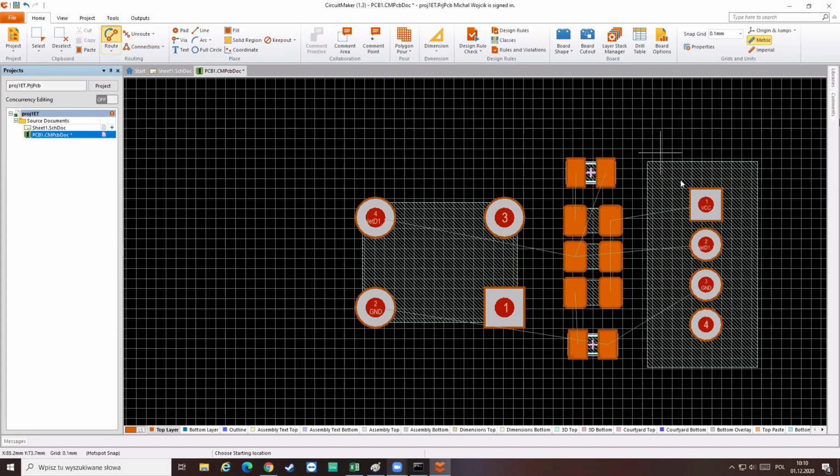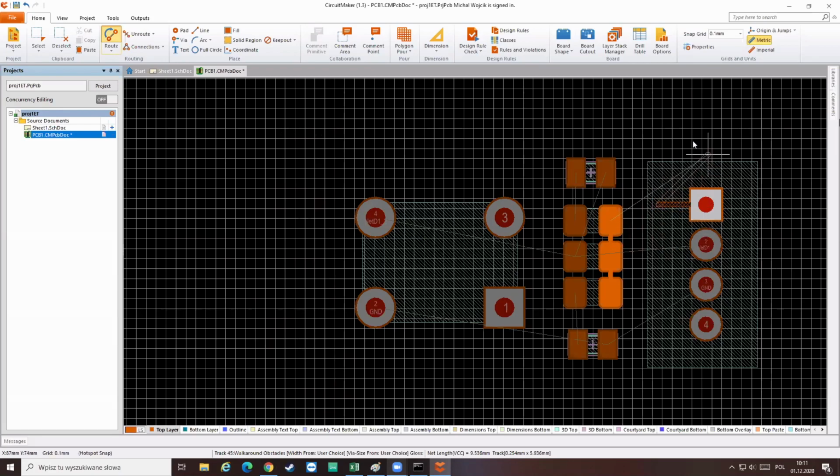So I take this routing tool and let's connect this together. Okay, let's start with these resistors and check out how to start it. I'm just left clicking, dropping the button. I'm not holding the button on my mouse, but I still have it in here and he's showing me the shortest path to go and also highlighting all the paths that I will need to connect together to be this VCC line. So let's start from one another. So left clicking here on this next path and left clicking here on this next path. Okay, now connecting this the shortest way. I'm starting from this left click again. Still didn't happen because every time you are edging a line, he's going to give you a different option to go. So I need to click several times actually to finish, and then right click of the mouse button, and I am free. And I have connected the very first line.